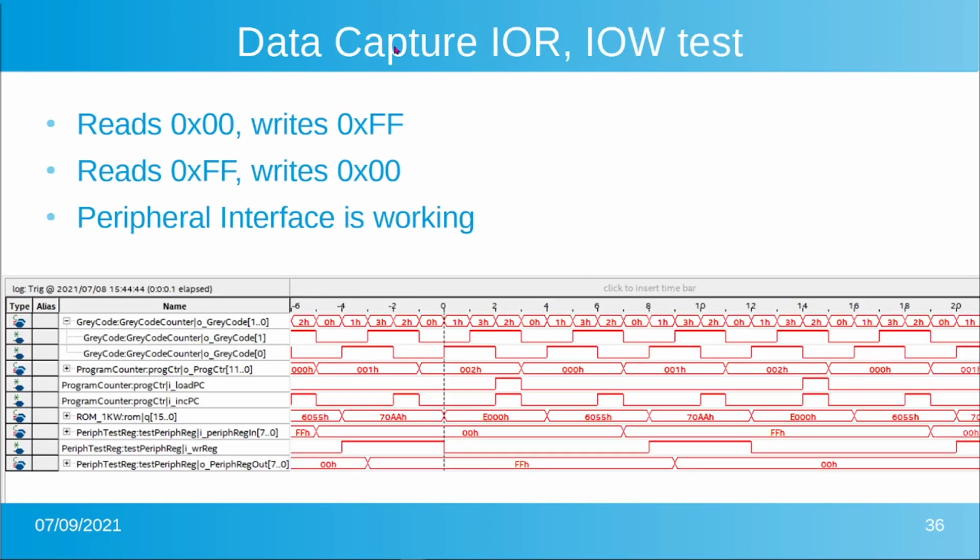So let's capture what that does. Wrote a little program that does that, and we can see it operating here. Quite a few more things on the waveform here. We can see the instruction running, the 605570AA. Notice the H is for hex at the end of it, the E000, and then the looping. We can see the address it's running through here. On the program counter, it's at 012, so it's a larger program. We're seeing more of the program counter work, enough to convince us it works.